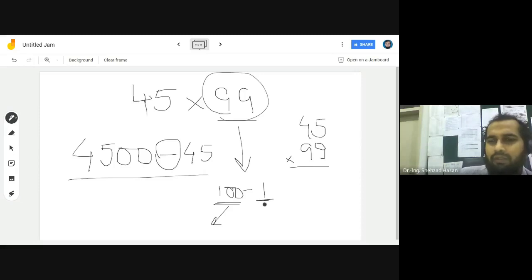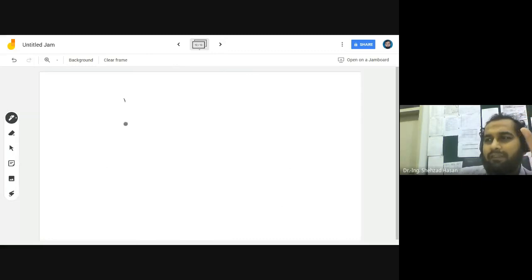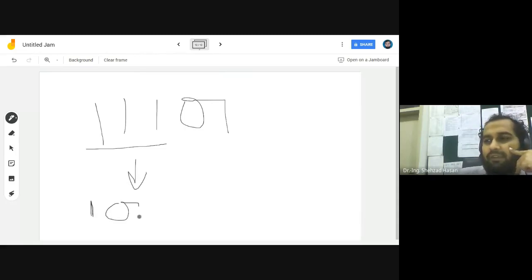That's also simple, right? So what I'm trying to say is, if you have got a binary number like 101 or 1101, something like that, you go for these sequences of 1s, and then you convert these sequences in a different way. So you have a 1 over here, some zeros over here, and a 1 over here. So you convert this thing into a different number. So 111 is actually this number here, 8 minus 1.